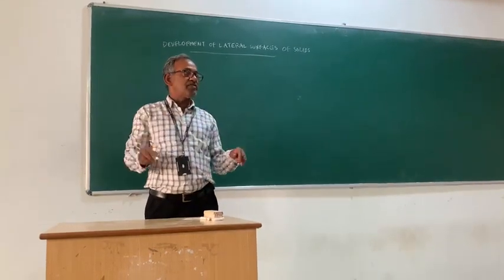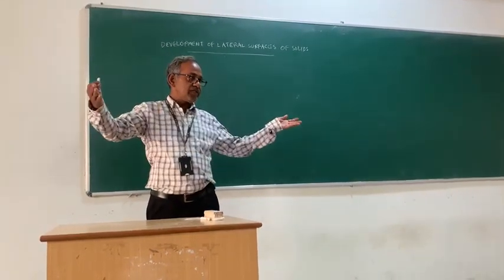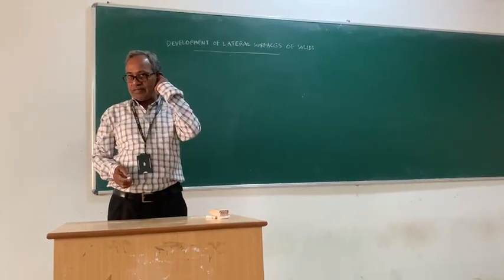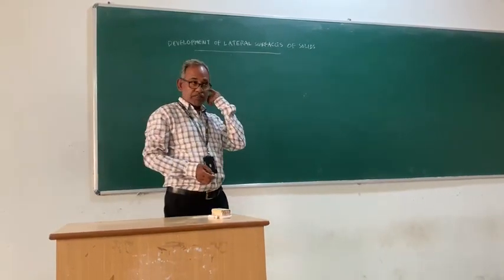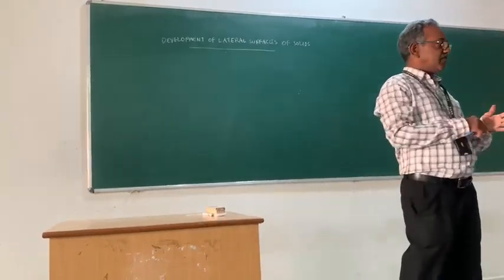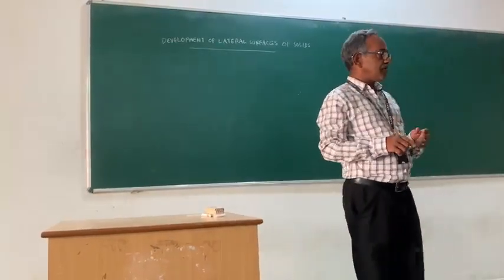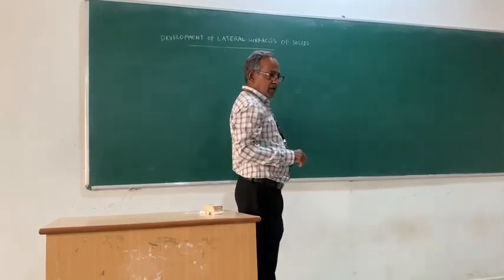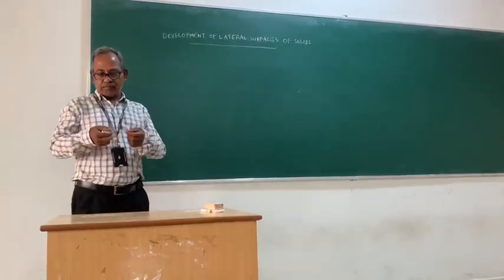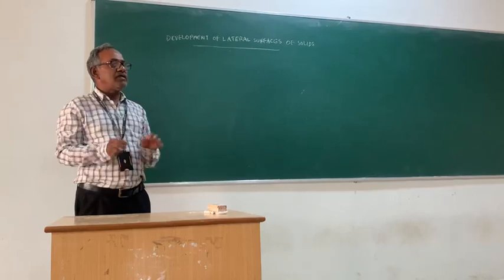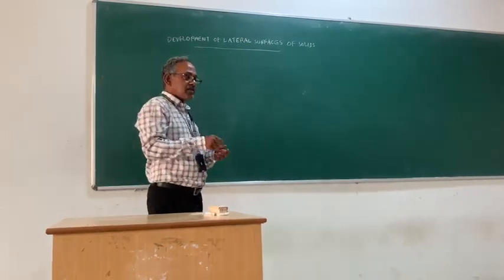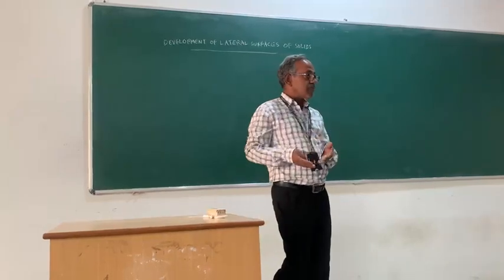A rectangular sheet we have cut from the bigger sheet. Let's say you made a rectangular sheet. How much sheet have you taken? A rectangular sheet of some 150 mm by 110 mm, and you have drawn some lines on it, and you have cut it accordingly, and small pieces were removed, and then you just bent it using the stakes and mallet and all that, right? To get that rectangular shape.